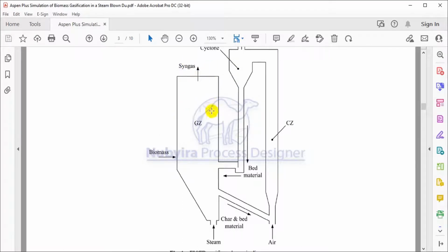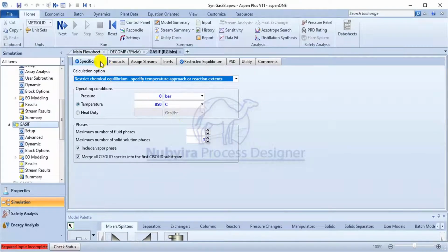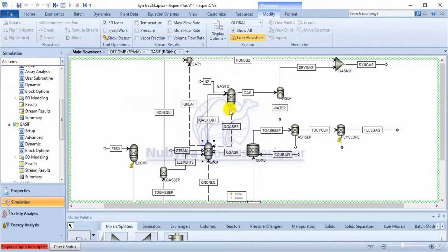We have this net gas coming here. You can see, I think it's a more realistic, more accurate model if you are able to integrate the heat out of the heat process. So that's why I did it. Now you can specify the gasification temperature in this stream here, and it will calculate the whole thing. And we have a calculator like the previous ones that will calculate the temperature here.